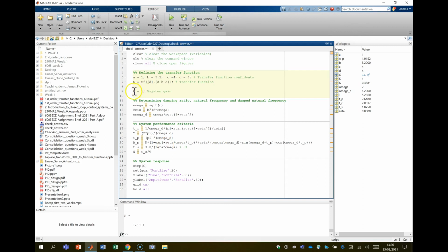One thing I should say is if you remember this K value here, the value being 1, you can see this is used here because it effectively multiplies the peak amplitude. When you haven't got a unit step input, the amplitude is effectively multiplied by that. So say for example the gain value was 0.5 or 0.2, you put the value there and that would dictate what your final value or your peak amplitude of the system is.